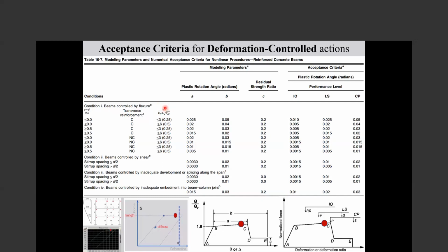The best option is that for each load combination, you change the properties of the hinges based on the V for that load, which is a little difficult. For each load combination, changing the properties of hinges is too much.